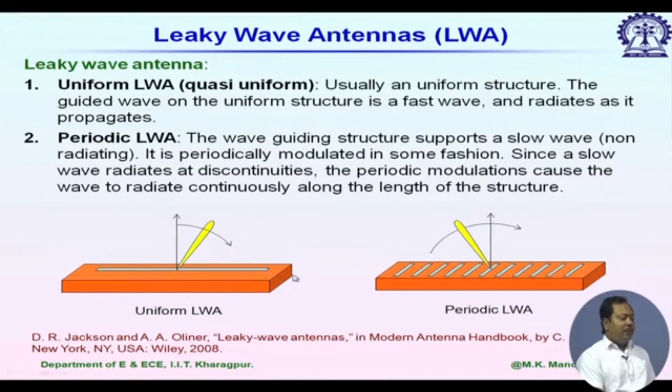and inside for fundamental mode operation we have TE10 guided wave mode. So, for this guided wave mode, then we have to consider both alpha due to the leakage loss and beta. Now, you see waveguide itself, it has some loss from the structure. So, whatever alpha we will be calculating here, it will be having the radiation loss and also the power lost inside the wave guiding structure itself. So, it has mainly two components.